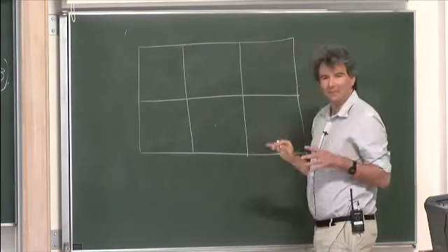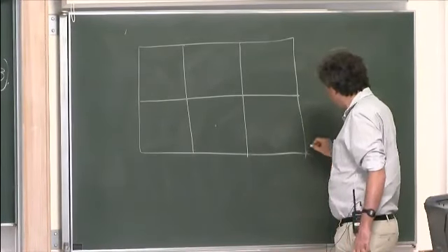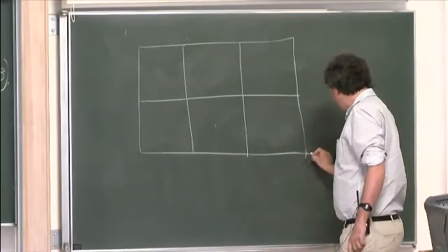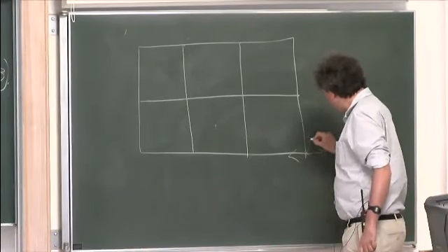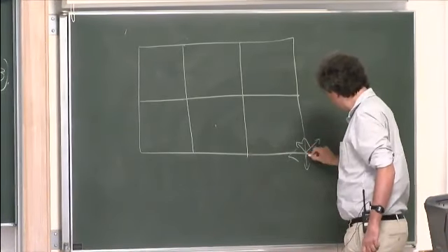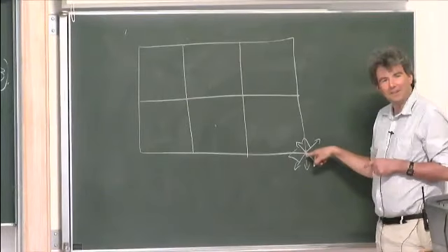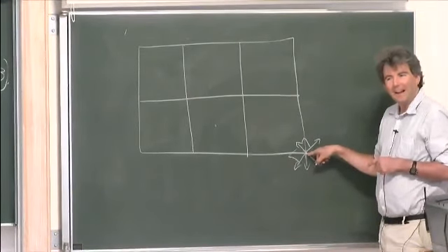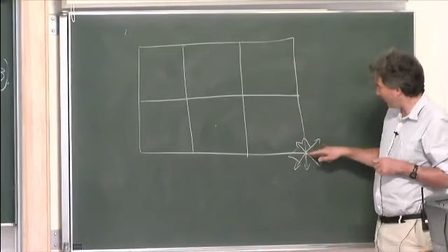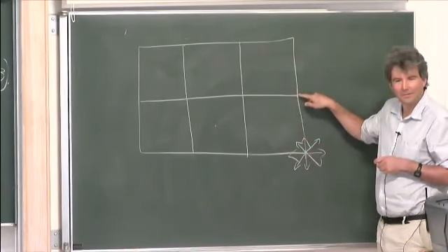So I've got a square grid, just as though I was doing a finite difference scheme, and at each point in the grid, I've got a set of 9 particles, and they have speeds attached to them, which I'll just draw with small arrows. So there are my 8 moving particles sitting at this grid point, and the time step is related to the particle speed, such that the particle that's moving up this way will hop from this point to this point in one time step.